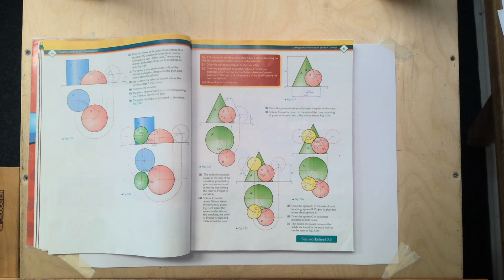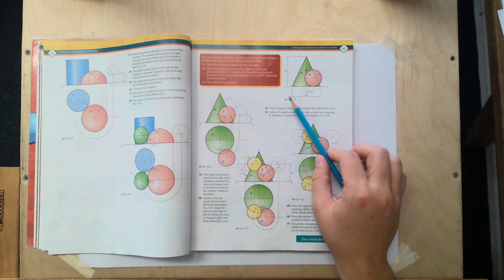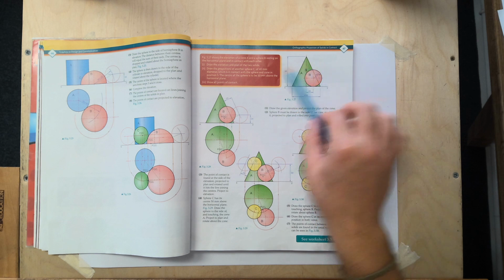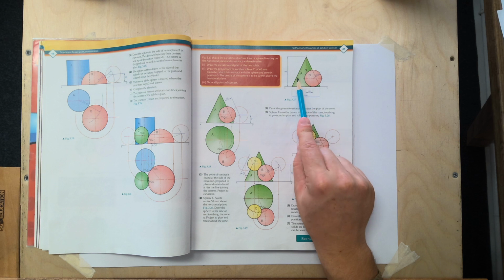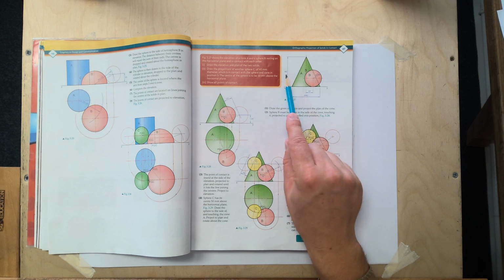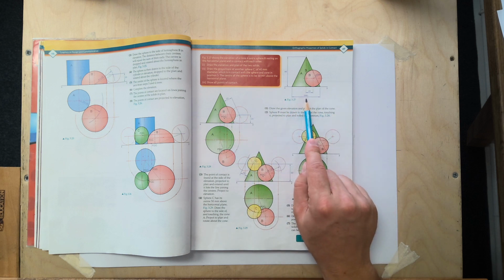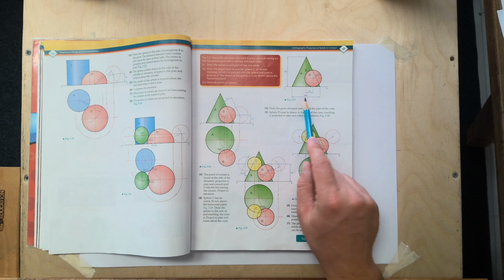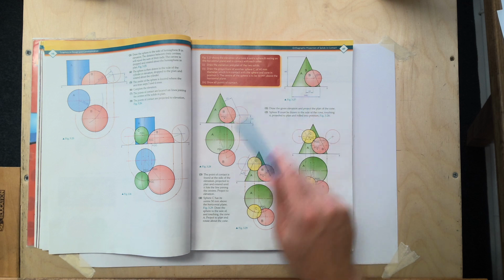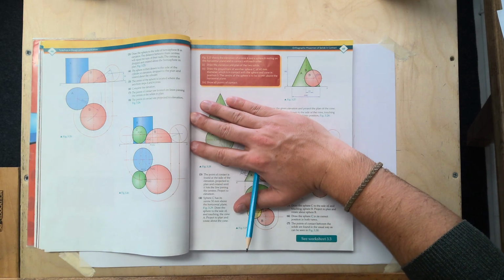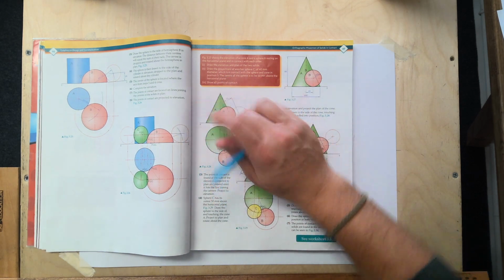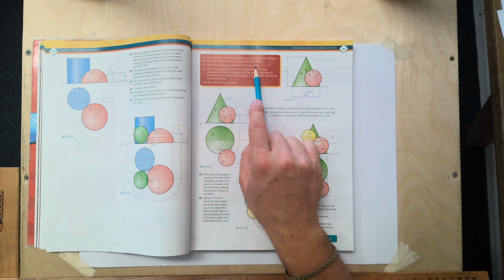So today's question is page 47, figure 3.27. They've given us an elevation of two solids, A and B. So cone A, sphere B. Cone A has an apex of 86 and has a diameter of 80, and sphere B has a radius of 24. And I want this first part, so remember, try not to be looking at all this, focus on the question itself. Draw the elevation and plan of the two solids.